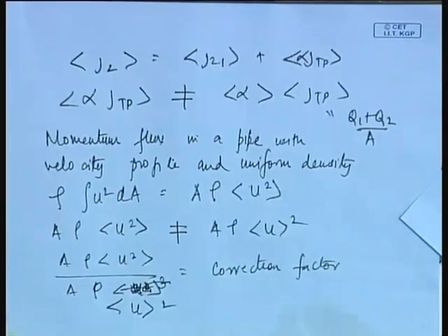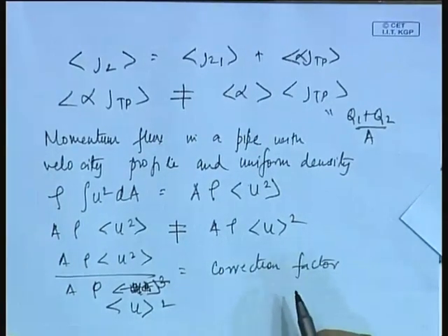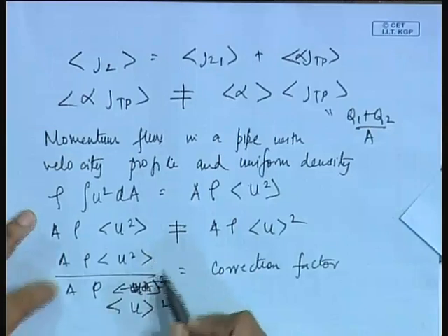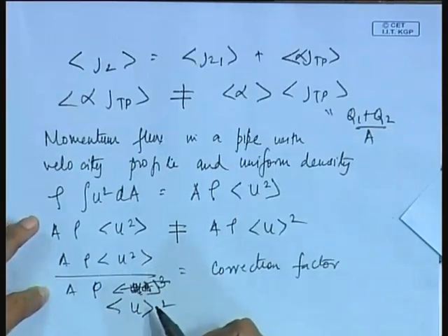So, usually what is the concept in single phase flows? We find that more or less the ratio of these is not very far from unity. And for truly one dimensional case, they become unity, because the velocity is the same for all points in the cross section.